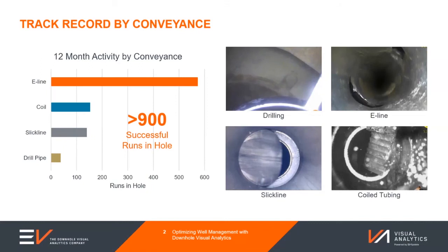We can also work on real-time enabled coil tubing. Now, whether it's electrically enabled or fiber optic enabled, we can do that in real time in those media as well. But if you haven't got that on site, if you are working on a more mechanical solution, whether it's production solutions in coil tubing or slickline, we have fantastic memory systems that allow us to get very, very similar, and in some cases, higher quality images using high density memory.